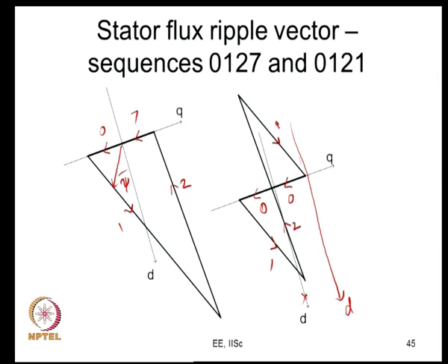So, we had also done this when we were analyzing the current ripple. There are quite a few papers which discuss these things in good detail now. Here what you can see is you look at your peak d axis ripple, you see a peak d axis ripple, here you see your peak d axis ripple. Your peak d axis ripple is much lower here, whereas your peak d axis ripple is much higher here. So, you are able to reduce your d axis ripple, this means a considerable reduction in your current ripple, though not necessarily in torque ripple.